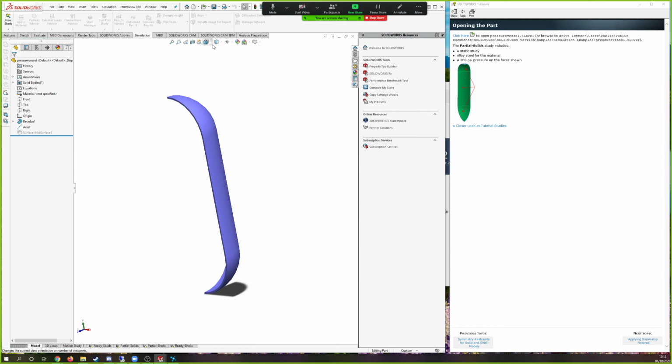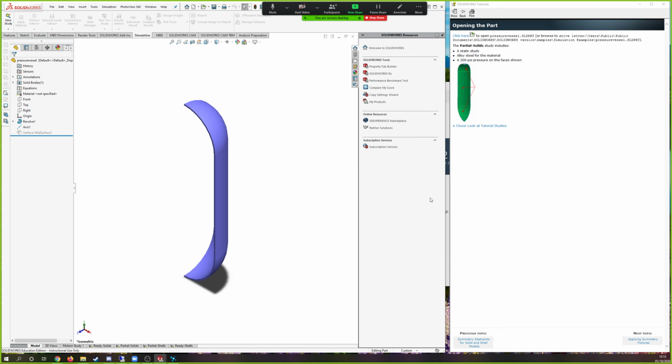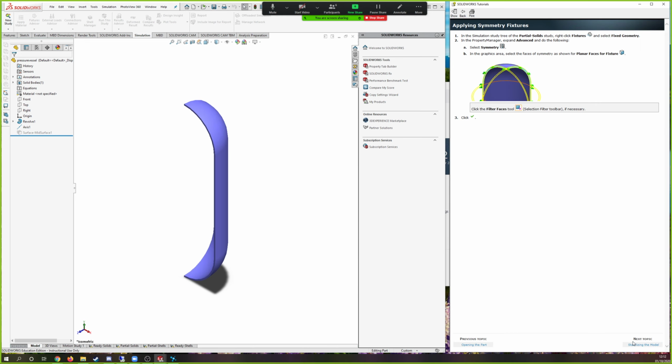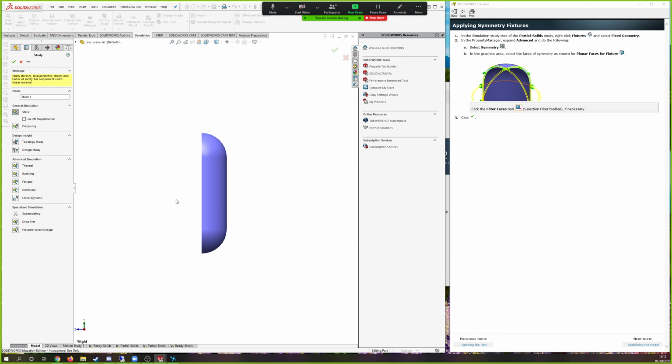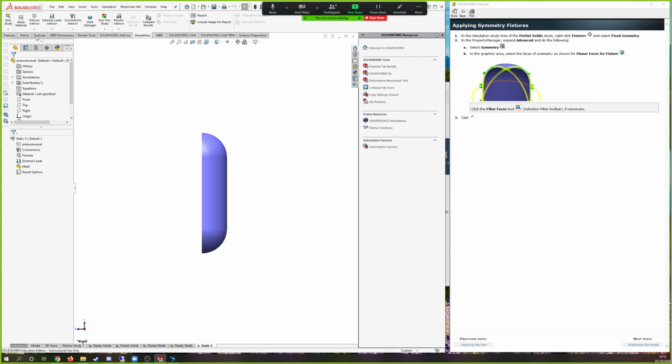Campbell, why did you say we only look at a quarter again? I forgot, I was a bit zoned out. It's to simplify the calculations. If you break that down into a certain amount of elements, it's less than if you're doing the whole body, which means you've got less calculations to do, which means it's an easier solution to run. It's not necessarily easier for you to set it all up, it's just easier for you to get results from it. It's just more simple, less calculations, less features. Gotcha.